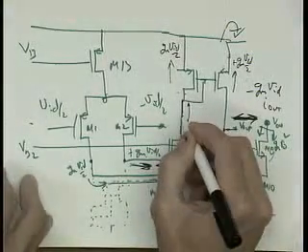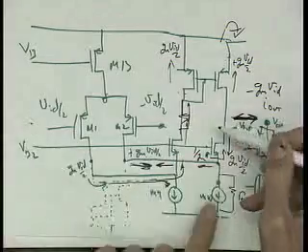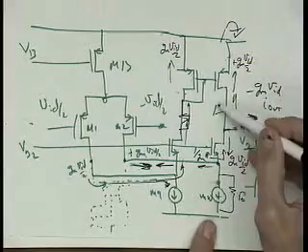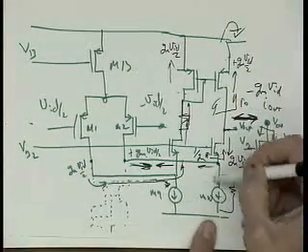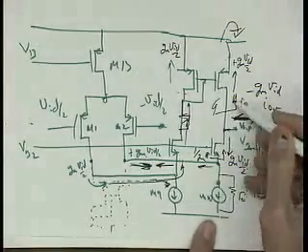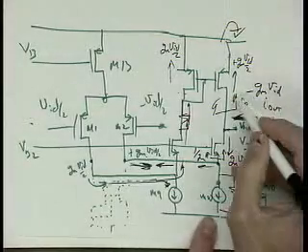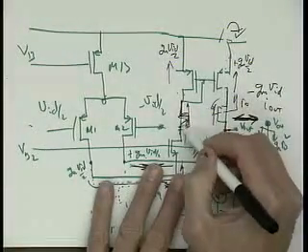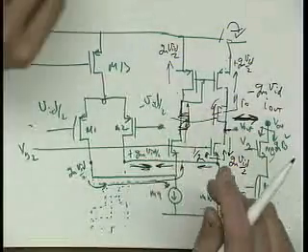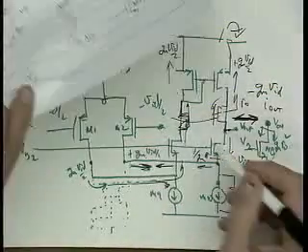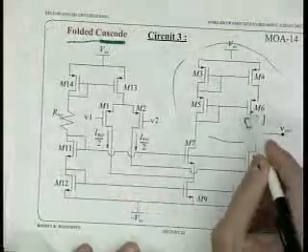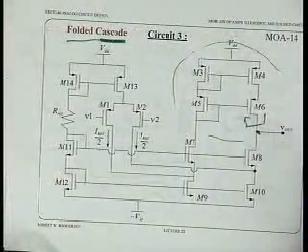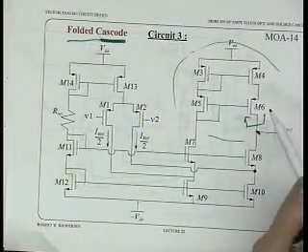Then we cascode this, right? If we just left it like this, the output resistance looking upwards would be what? Just R0, right? Looking down would be Gm R0 squared. So we'd only get an output resistance of R0. So we need to cascode this upper part as well. We put cascodes up there, go off to another bias string, and we end up with this. Or we can do it like I did here, right? You could take us to another string, or you can diode connect it like this. There's a couple ways you could do it. So you got it? So see how it works?